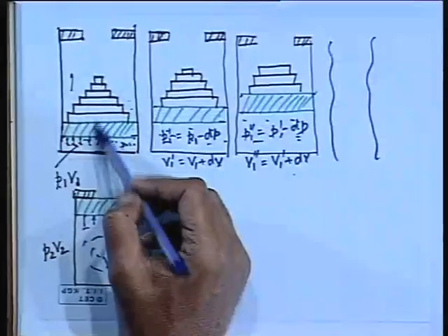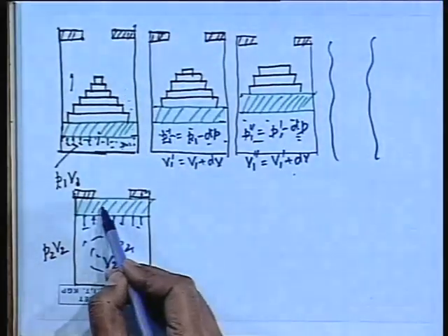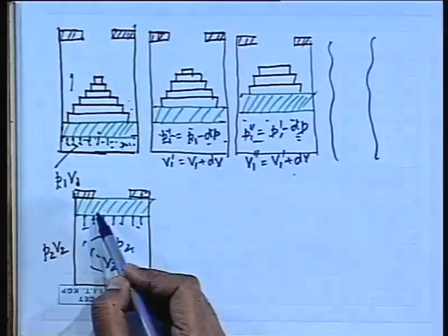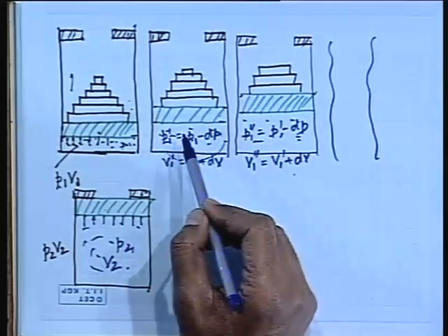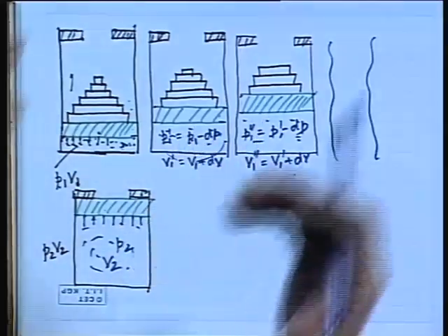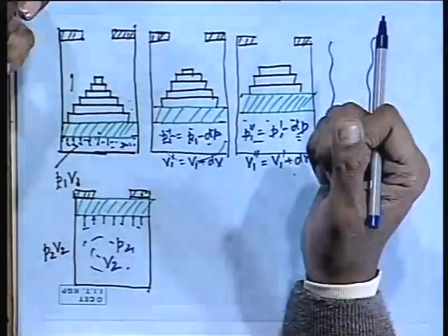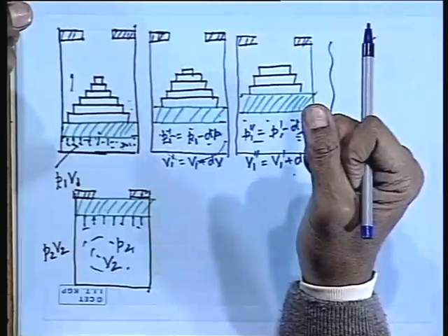You understand, slowly the piston moves from an initial pressure P1 and volume V1 to an intermediate pressure which is slightly less than P1, volume slightly more than V1, and then again slowly if we remove, and do like that after a long time with infinite resolution of this weight, the piston will come here. And if we do this, then what are the differences? Then all the intermediate state points are almost in equilibrium. That means they are in thermodynamic equilibrium in the limit.